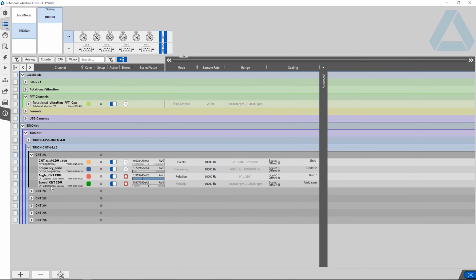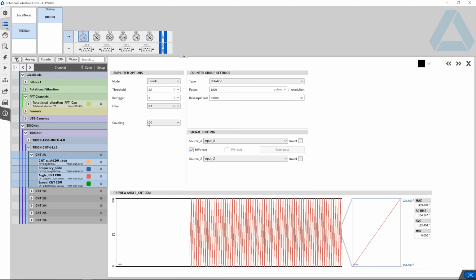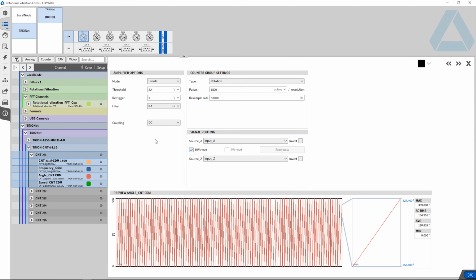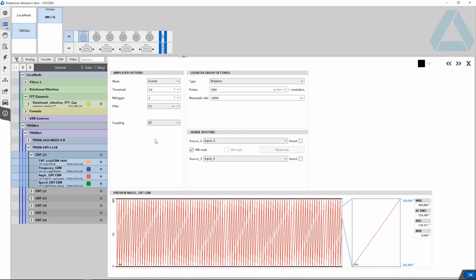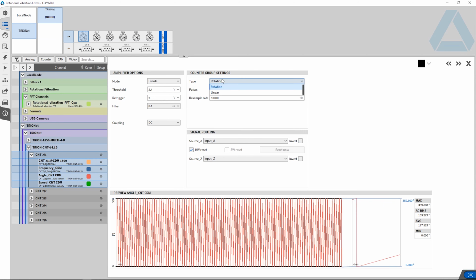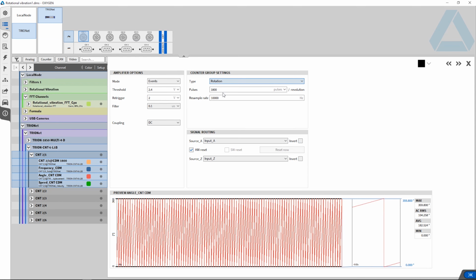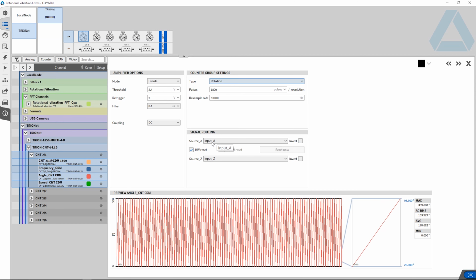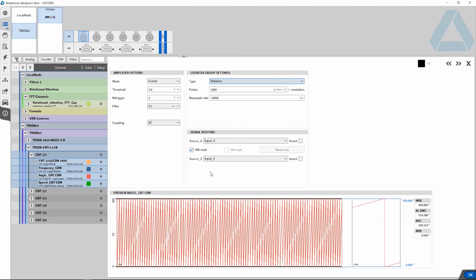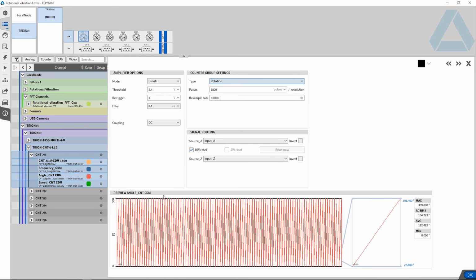Setup at the counter. I go to the counter setting. We can see here on the left side the input channel. So we have free programmable thresholds when you use other sensors. This is related to rotation, so we get 1800 pulses per revolution, and we have the A input, and we use the real hardware reset with the set input, so we get here the absolute angle